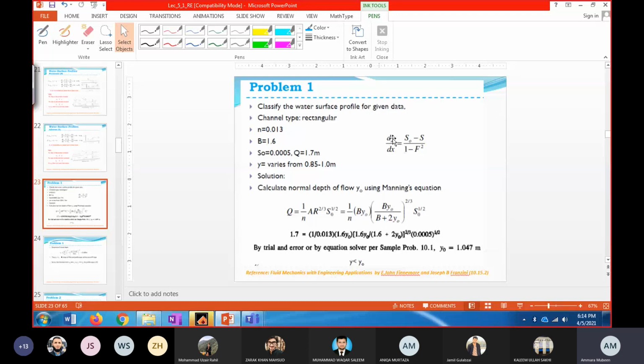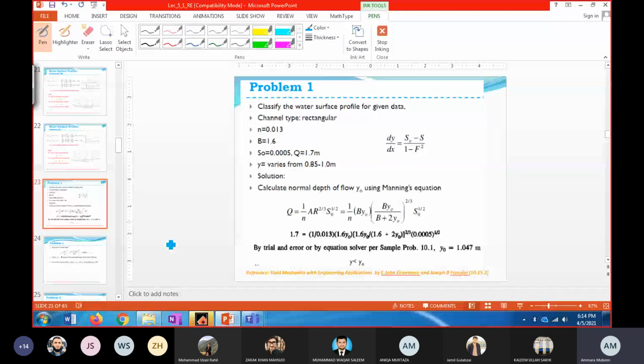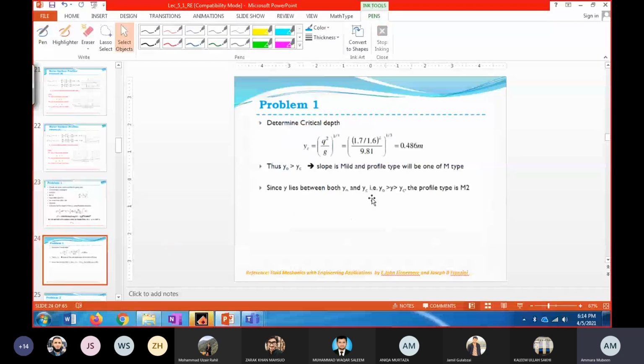And if I ask you about dy by dx, so here we have Y naught greater than Y and it is greater than YC, so that is why it is M2.